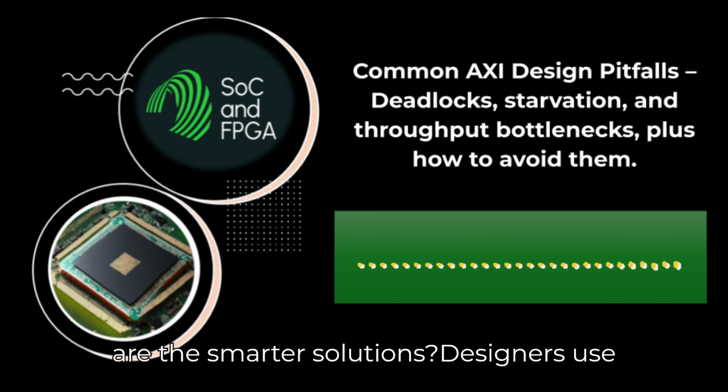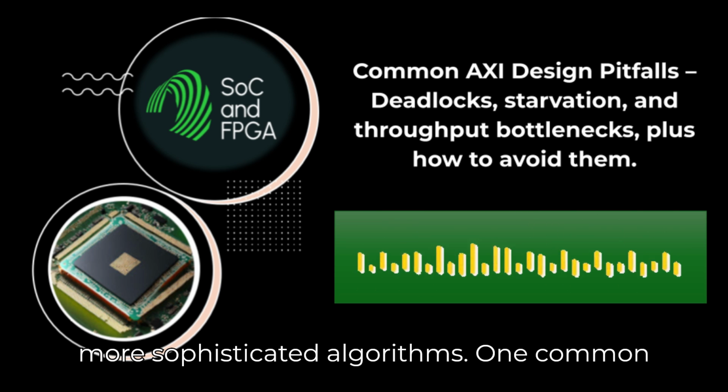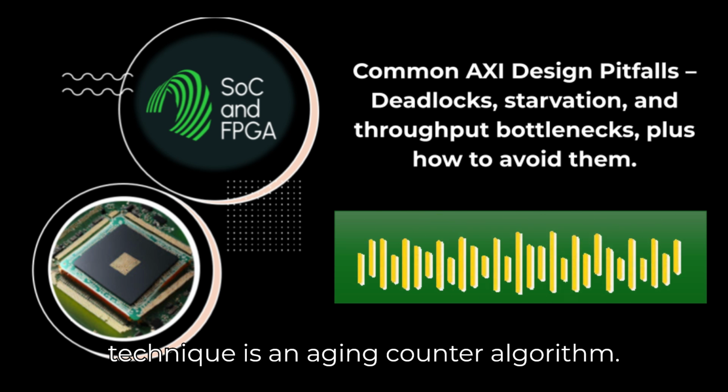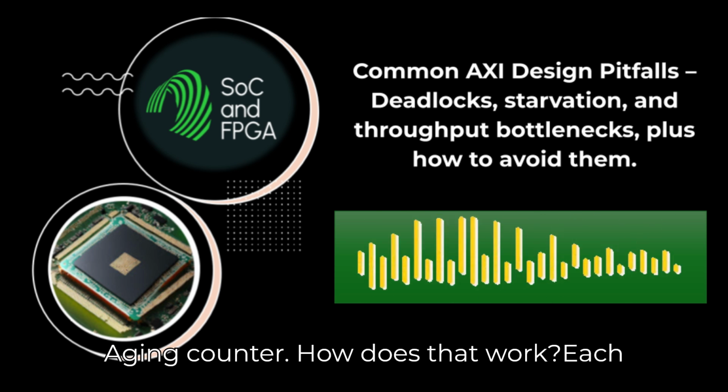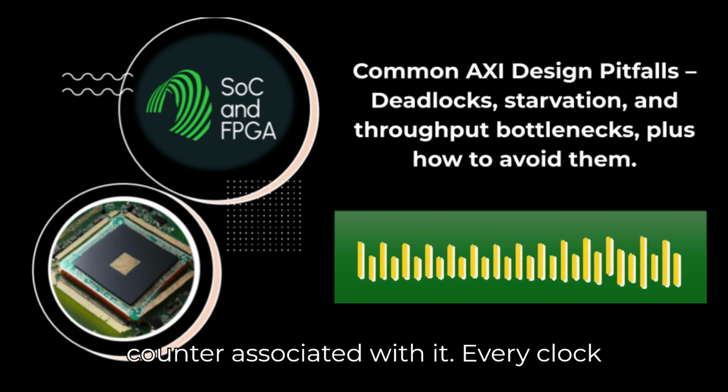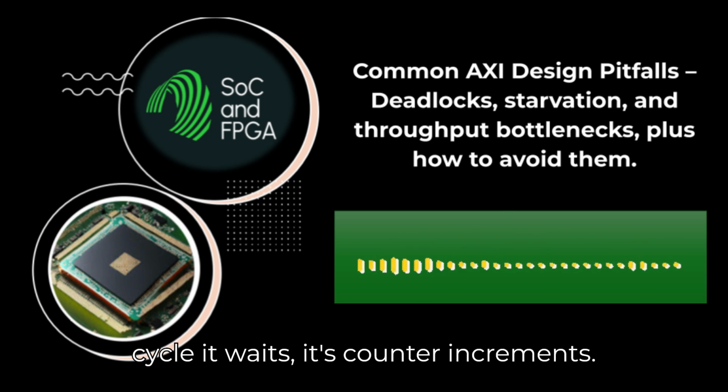So what are the smarter solutions? Designers use more sophisticated algorithms. One common technique is an aging counter algorithm. Aging counter, how does that work? Each master that's waiting for the bus has a counter associated with it. Every clock cycle it waits, its counter increments.